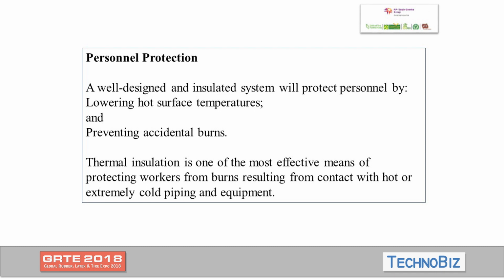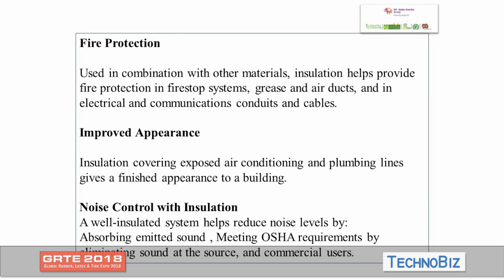It helps personal protection, like accidental burns or some other accidents, because the hot surface or the very cold surface is protected with help of insulation material on top. It also helps as far as the fire protection. It gives a better improved appearance. The noise control, the noise is very much under control.